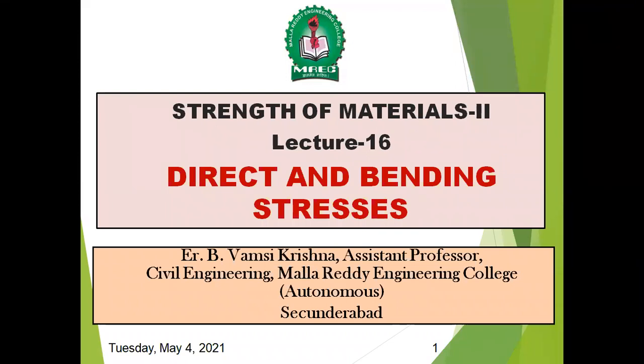Now we will go into our topic, which is direct and bending stresses. A member which is subjected to both direct and bending stresses is one that we must consider as a combined stressed member. Why is it called a combined stressed member? Individually, if the member is subjected to longitudinal load, it will be subjected to longitudinal stress or direct stress. If a beam is subjected to vertical load, it will have a bending stress. Those are individual stresses and individual loads. If a member is subjected to a load which creates direct and bending stresses together, that member is called a combined stressed member.